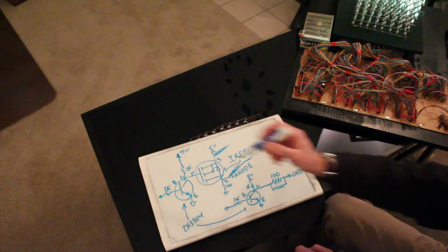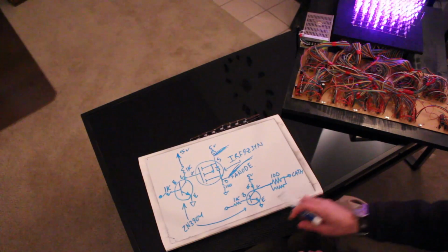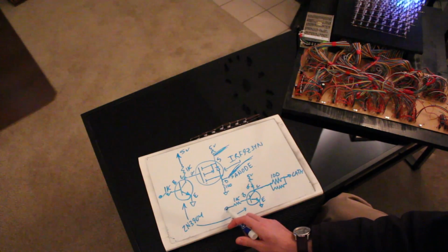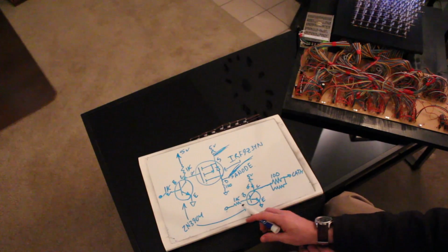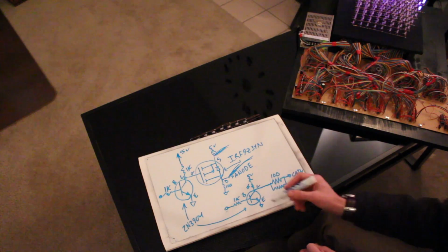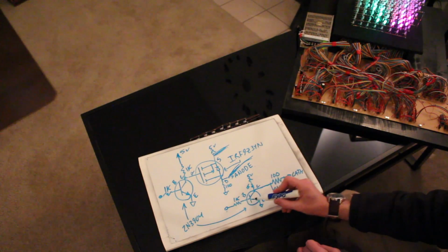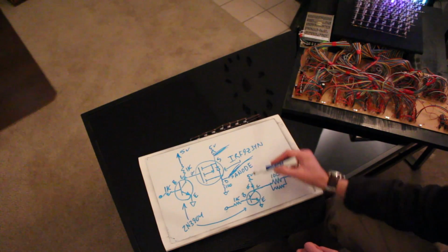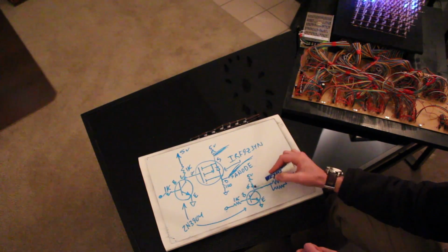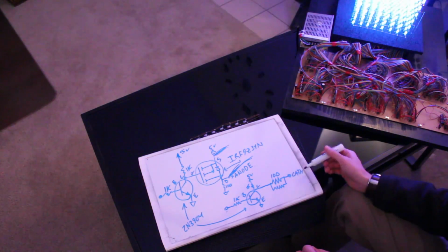So we have 8 of those. Then down here is the cathode control circuit. This is the input pin, so this is where the output of the shift registers goes, drives a 1K to another NPN BJT type transistor, and this again is a 2N3904. And so we're saturating this transistor here, and then there's a 1K here to pull it up to 5 volts, the collector pin. So when it turns on, it basically pulls this low. And what we're pulling low is right here.